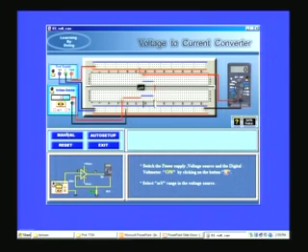Right, once it is done, let us switch on the power supply, multimeter, and I give some millivolts. So when I give about 100 millivolts, this resistance is about 10 kilo ohms. So 100 millivolts by 10 kilo ohms should give me about 10 microamperes or something like that.